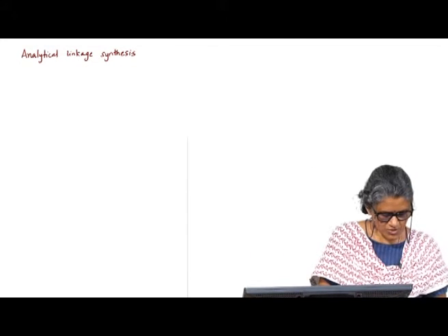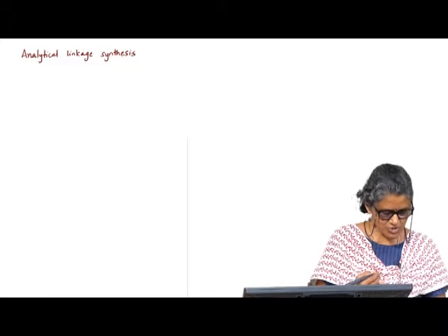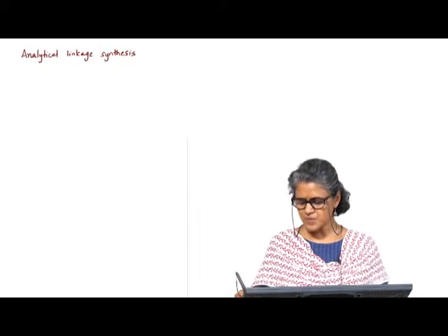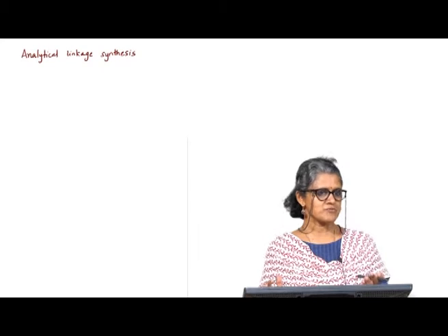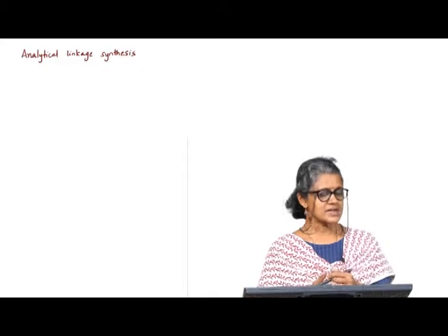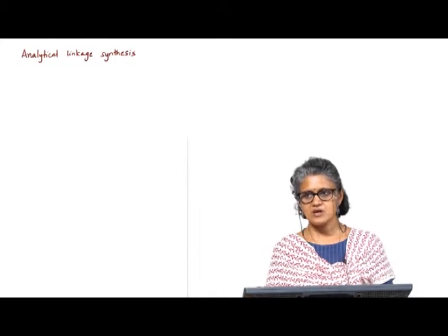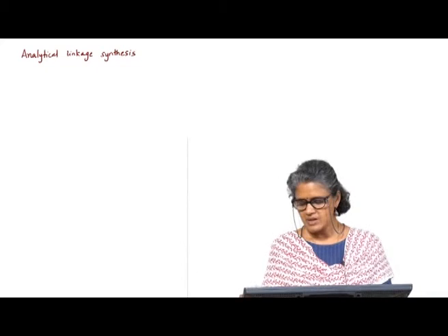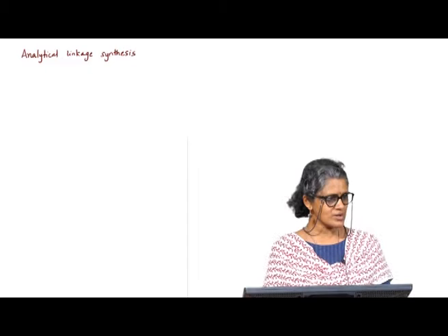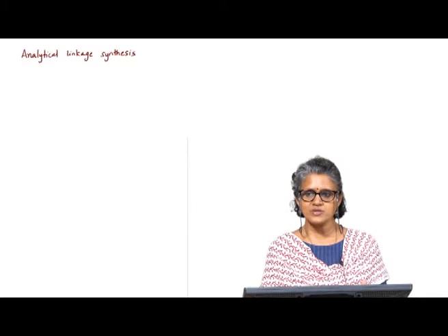Okay. So the instantaneous kinematic conditions are also a key reason why you might want to look at analytical linkage synthesis. The Chebyshev spacing that we looked at would be the first step. If you want to design a linkage, you would first analytically determine, for a case where it satisfies the conditions for using Chebyshev spacing, the precision points. That would be the starting point for your design.